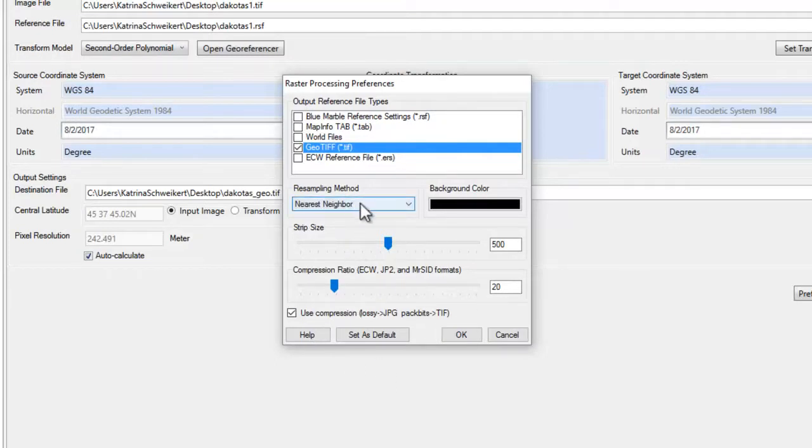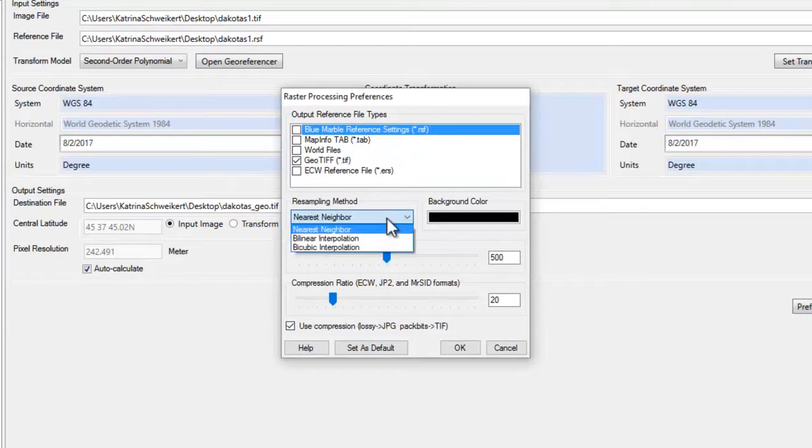We can specify what output file formats we want. This is a GeoTIFF, so I'm just going to stick with a GeoTIFF header. And some additional settings. Again, we're going from orthogonal to pixel grid to orthogonal to our geographic coordinate system, so there is some resampling happening. So we could specify methods depending on the input data type if it was necessary to recalculate some of those values.